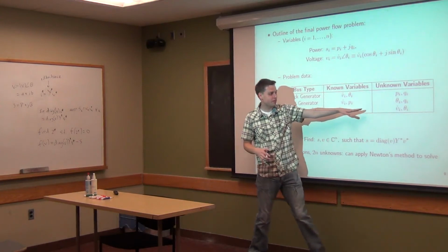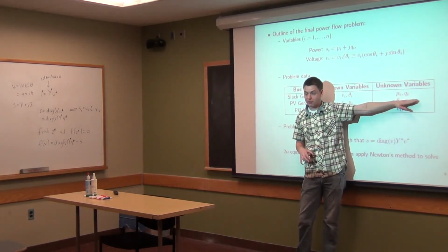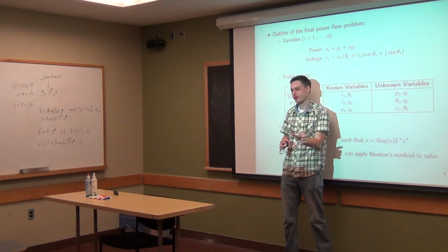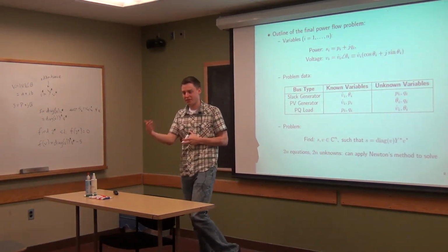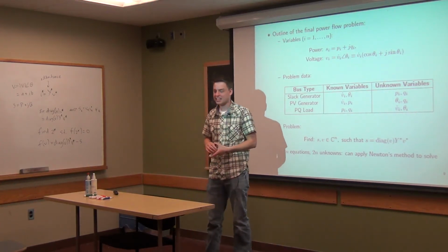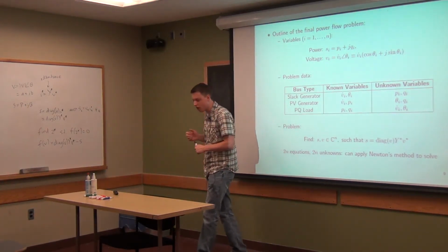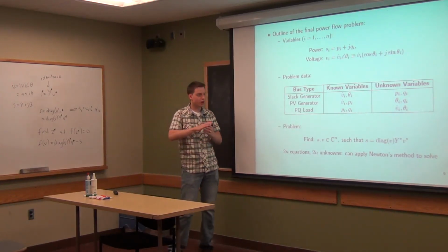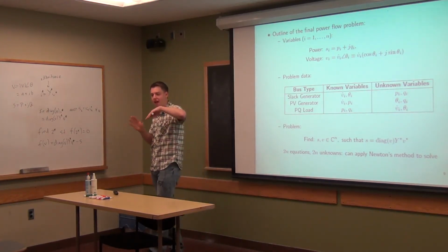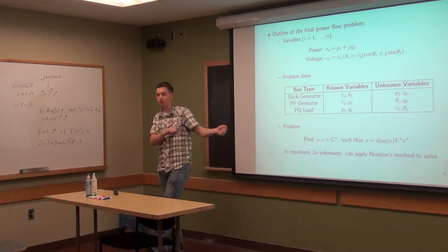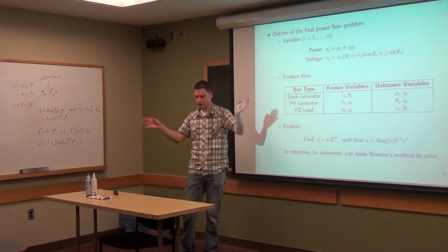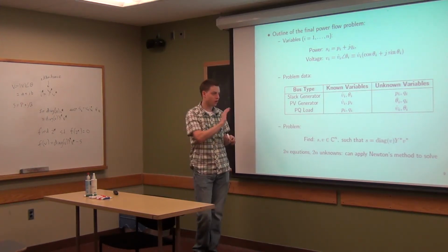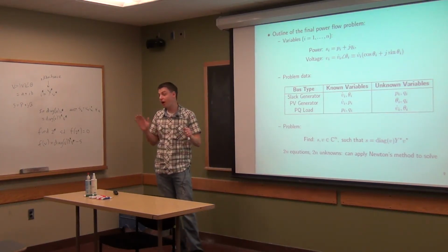So yes, they are different angles. It's very common for them to be different angles, but you want that to not be too big, where too big can be 10 degrees, 20 degrees maybe. Getting much bigger than that, you can start to get a little nasty. And in fact, there's a lot of analysis out there on angle stability, showing plots of what angles a system can be stable for and what it can't, and where in this plot of angle changes your system will start collapsing. So this is all very important, but in general it's fine and common.